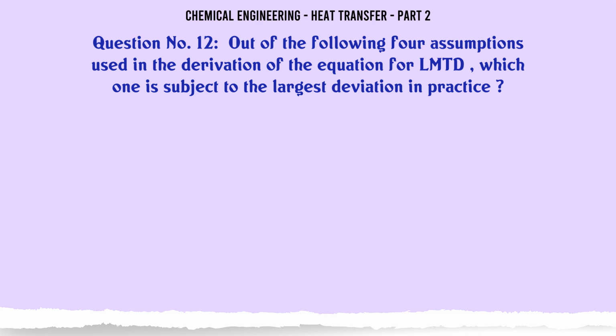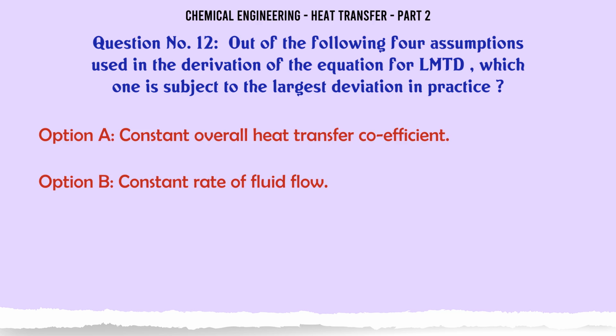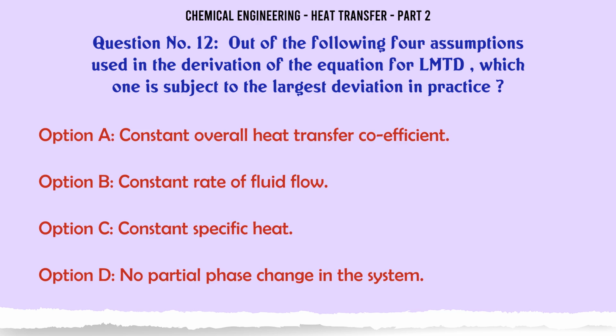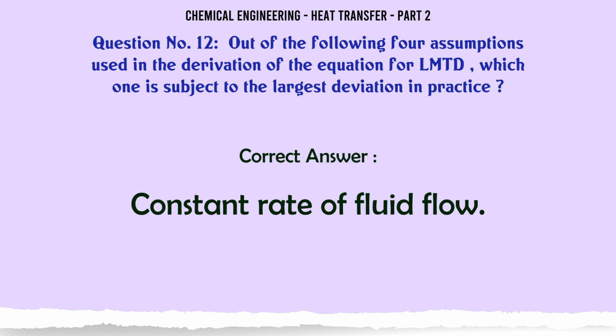Out of the following four assumptions used in the derivation of the equation for LMTD, which one is subject to the largest deviation in practice? A. Constant overall heat transfer coefficient. B. Constant rate of fluid flow. C. Constant specific heat. D. No partial phase change in the system. The correct answer is constant rate of fluid flow.